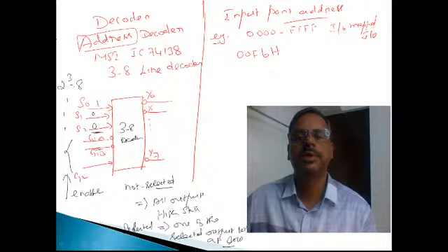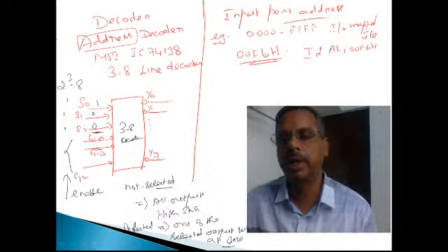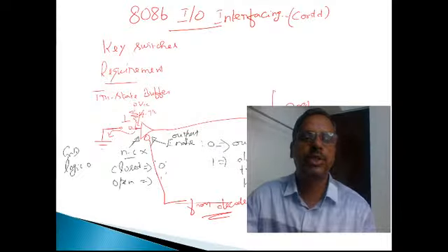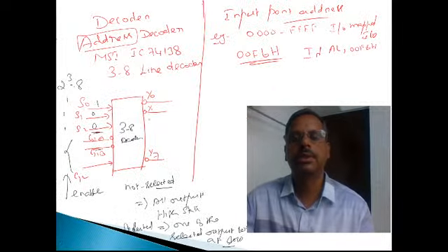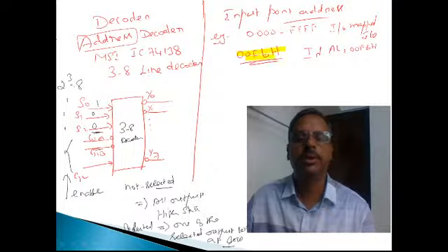Right, F6. So in my assembly language program, when I do IN AL, 00F6h, I expect that the accumulator's 0th bit will have the switch status, and your design should be such that this tri-state buffer is enabled at the address 00F6. This is only an example. You people can try with something else also. That's the idea.